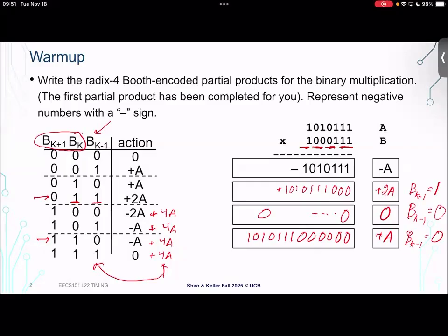These b sub k minus 1 operations feel sort of like a carry. They're not a carry, right? We're not doing addition yet. We're just generating the partial products. But it's the same idea as a carry, where once you get enough significance in the current column that you're looking at, you add something to the next column, the next set of bits. Okay, and then we're not going to do it here because I'm confident that you all can do it, but the final step would be to sum the partial products to get the result.